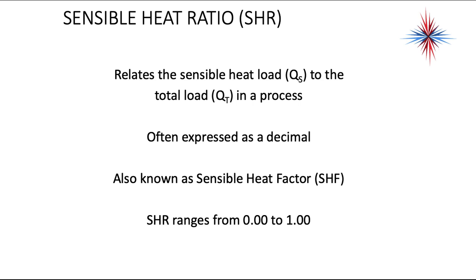The sensible heat ratio is a relationship between the sensible heat load, that's the temperatures I can measure, to the total load in a process. It's a decimal. It's sometimes known as the sensible heat factor. It's the same thing. Sensible heat ratios range from 0.00 to 1.0.